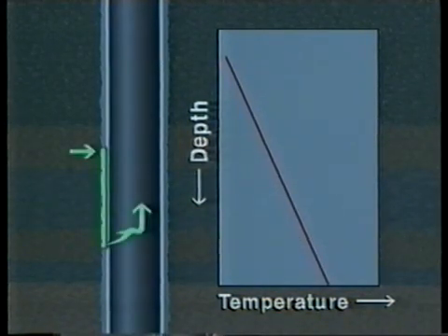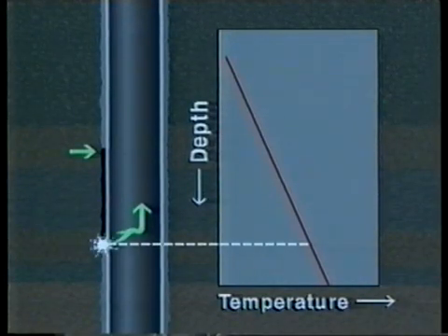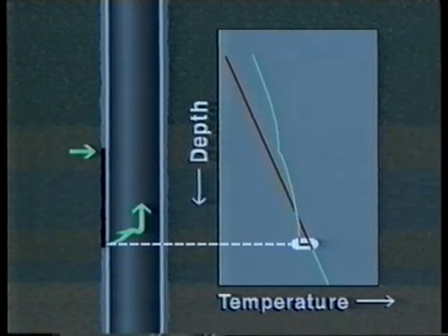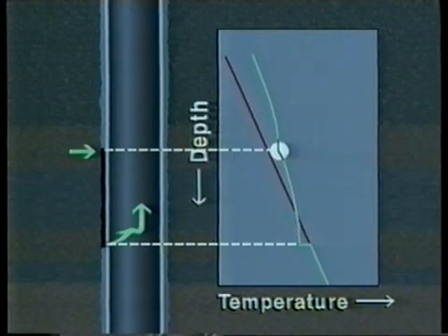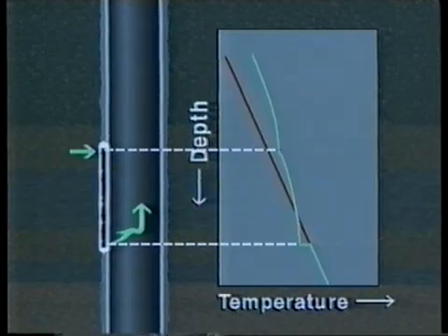In the case of a channel above the perforation point, the flow meter again shows the entry point into the wellbore. The temperature survey indicates cooling there and suggests a gas entry. But the temperature survey also indicates another point of cooling. When the fluid identification device confirms that the produced fluid is a liquid, the confusion is explained as a channel from above.